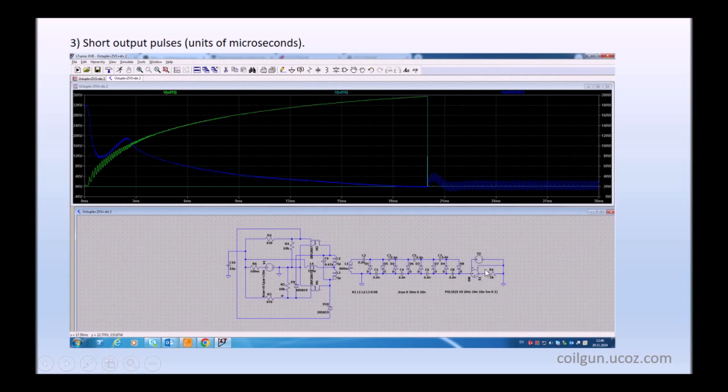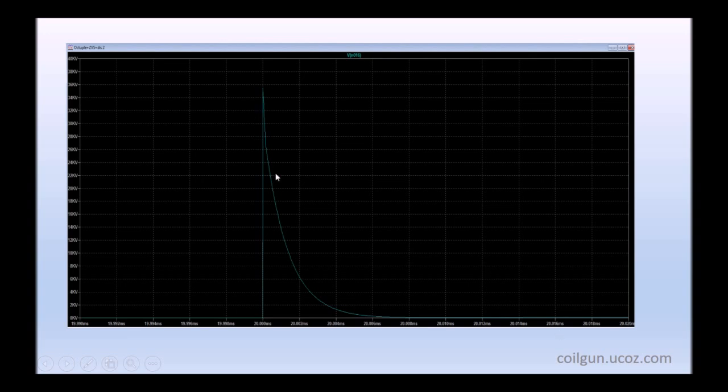It's a 1 kilo ohm load. According to our previous video, it is equivalent to the load of a human's body. And you can see that when this switch is closed, it means that discharge takes place. You can see that the pulse is very short. Its half width is only maybe 1 microsecond or less.